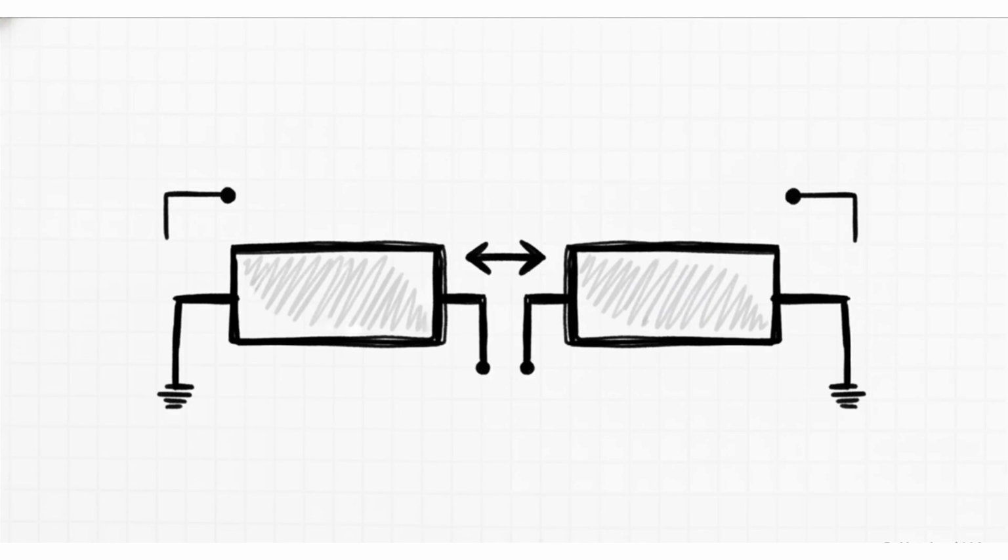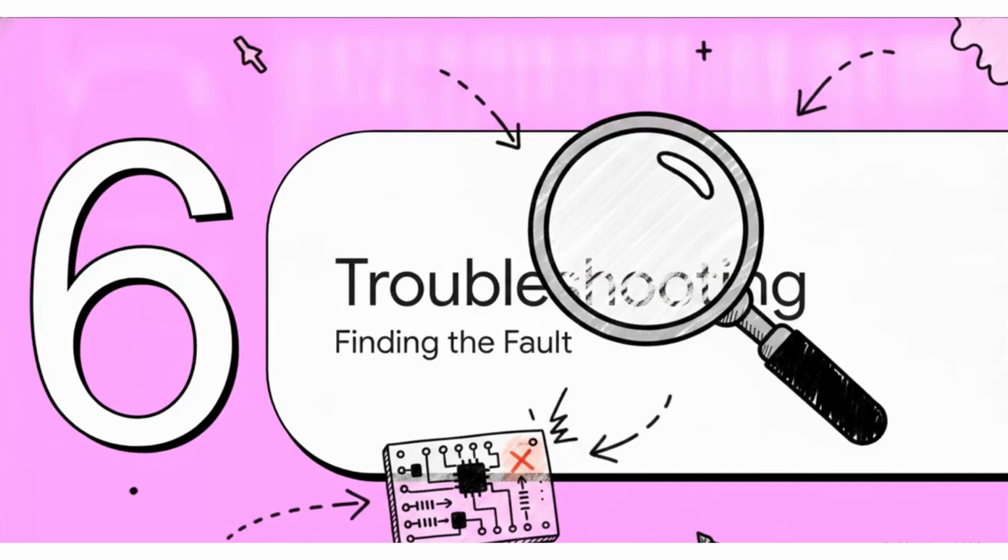And what about high-precision analog circuits, things like integrated resistive voltage dividers? Well, here, the physical layout on the printed circuit board is honestly just as critical as the part itself. Designers have to follow some incredibly strict rules, aligning the matched elements perfectly side by side, maintaining exactly equal spacing, and orienting the board perfectly orthogonal to the factory printing direction. Doing all this minimizes spatial variations and makes sure the voltage ratio stays rock solid even against crazy temperature and voltage swings.